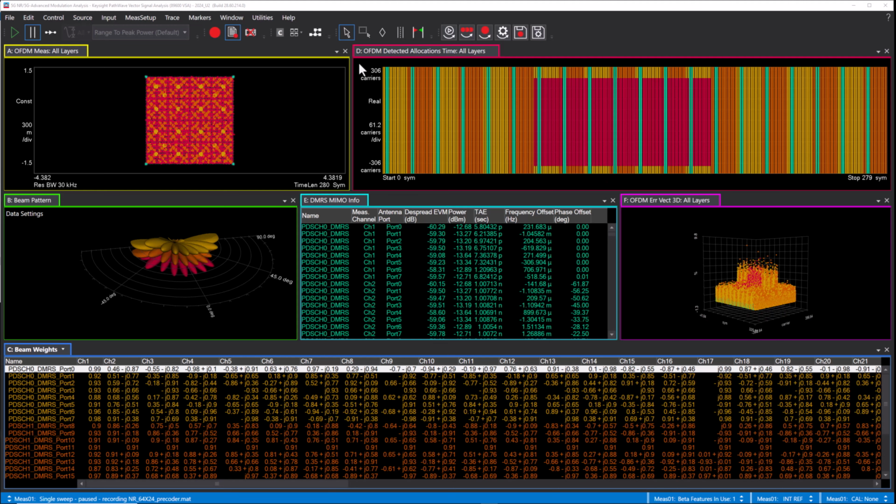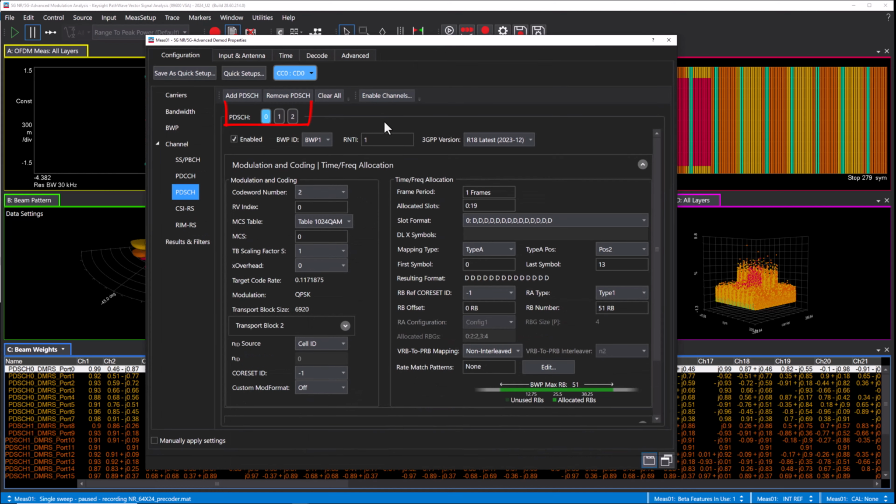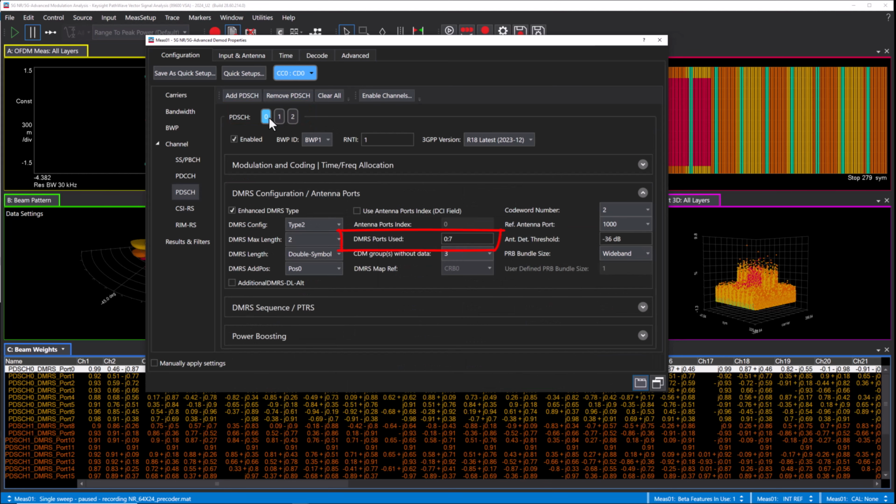In this 89600 multi-user MIMO example, 3 simultaneous users use the same time and frequency resources, each with 8 antenna ports or transmission layers, with a total of 24 ports. This, for example, could also be configured with 24 users, each with a single antenna port.